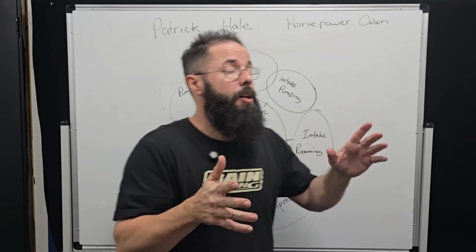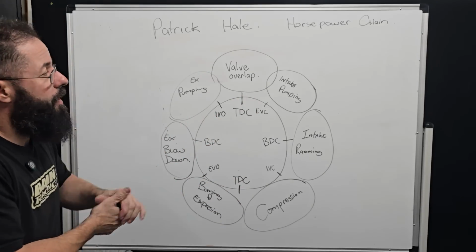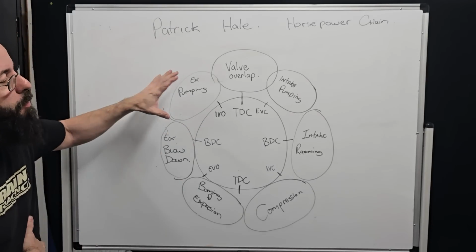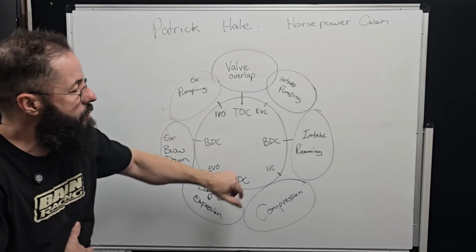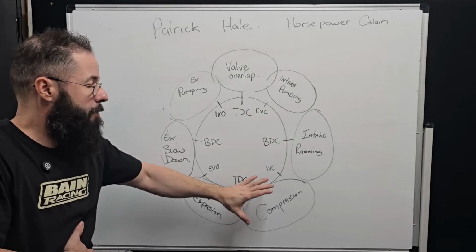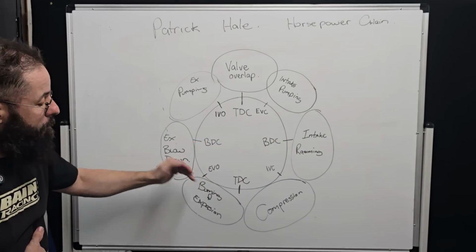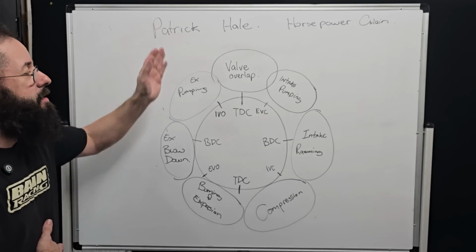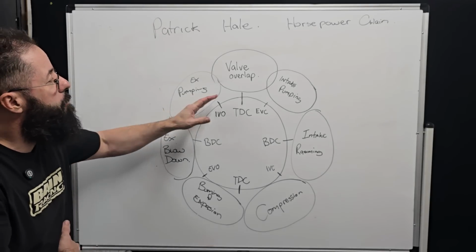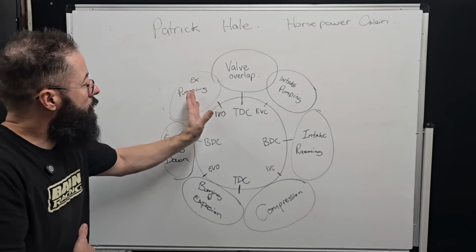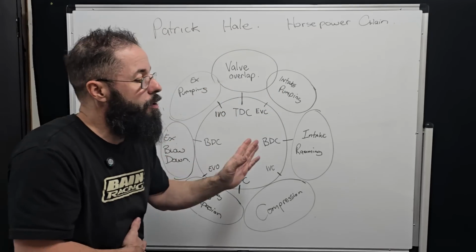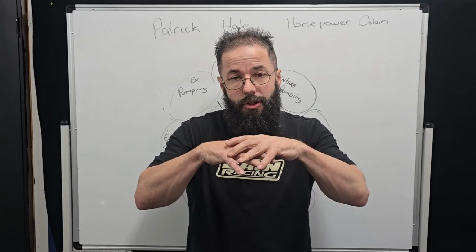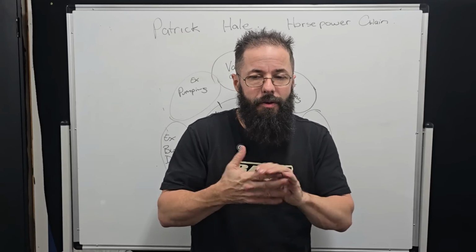But yeah, again, I thought I'd share this. It's a very, very old principle. Again, I learned it from Darren Morgan, but it's a principle that might help you understand everything that's happening with the ramming, the compression cycle, the burning, and then the expansion, our blowdown phase, our pumping phases, the velocities running down the pipe, our overlap, and the correlation between these two, which is really, really important. This is why I say the LSA needs to be based on the type of chamber you have, right?